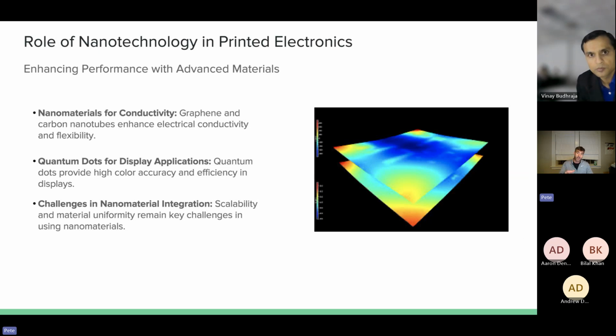The reason being is all of these technologies come in contact with the air, and as soon as anything in a highly volatile solvent comes in contact with air, it'll dry up and that tends to clog. So inkjets and aerosols tend to have clogging issues. We have less of that because the meniscus of the fluid is actually in touch with the substrate. So the cavitation within the dispenser, along with the constant wetting of the substrate, reduces it. But if your solvent is very volatile, it still will dry pretty quickly.